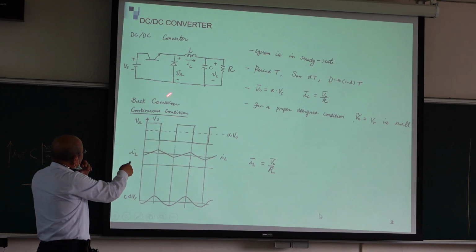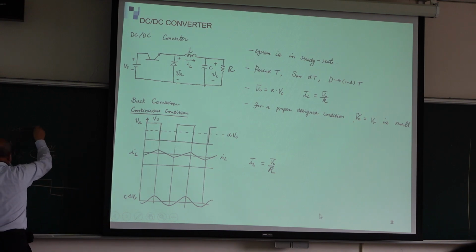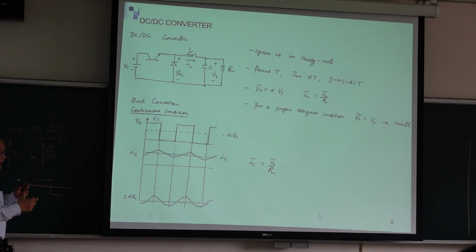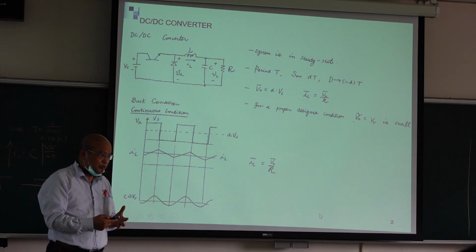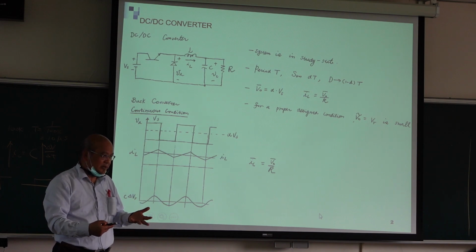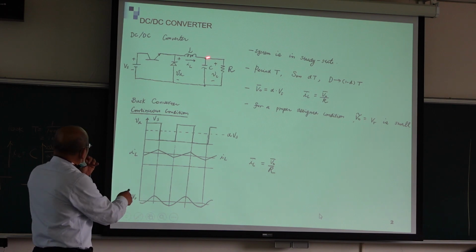So we have a switching frequency. If the switching frequency is 100 kilohertz, what is your time interval? It is this one, so it is 10 microseconds. Every 10 microseconds, you have to do one switch. So from this one to this one, 10 microseconds. Do you think that 10 microseconds is very long or very short? Very short. Can you use a computer to calculate it? Maybe no. So you need hardware. We need a quick switching.